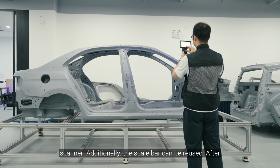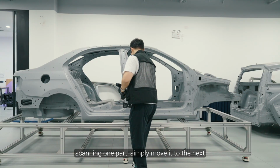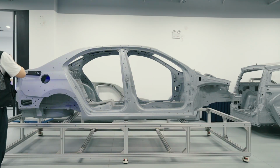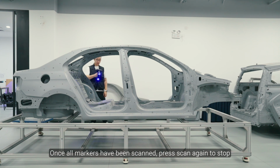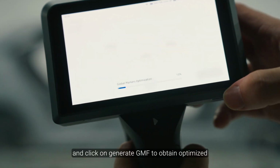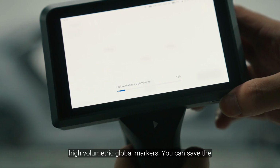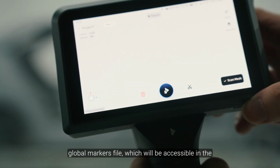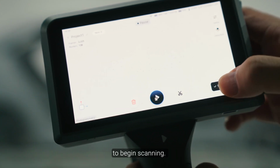Additionally, the scale bar can be reused. After scanning one part, simply move it to the next area and continue to scan global markers. Once all markers have been scanned, press scan again to stop, and click on Generate GMF to obtain optimized high volumetric accuracy global markers. You can save the global markers file, which will be accessible in the Resources section. After that, press Scan Mesh to begin scanning.